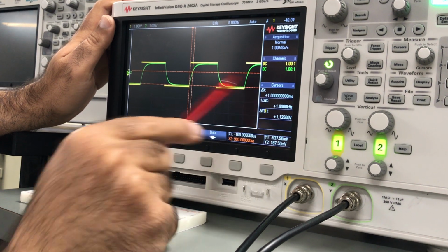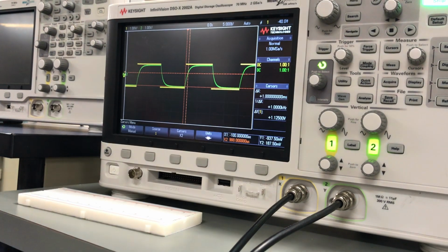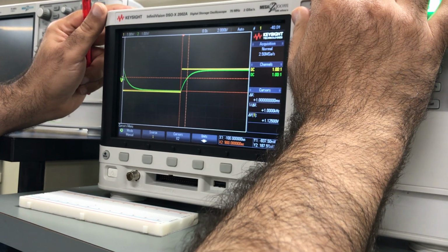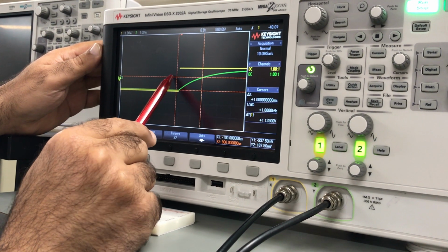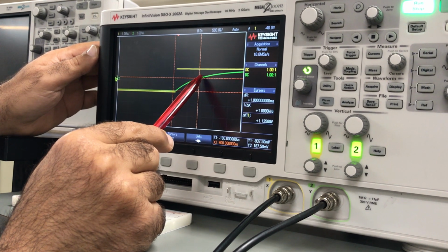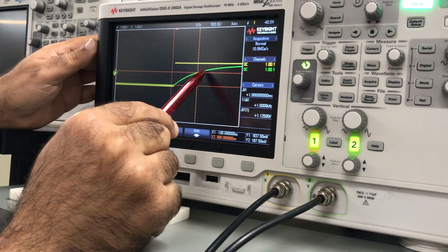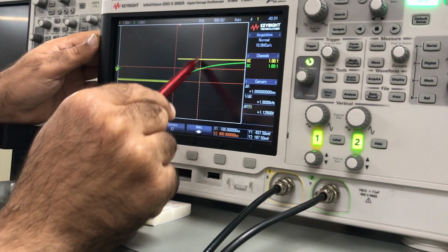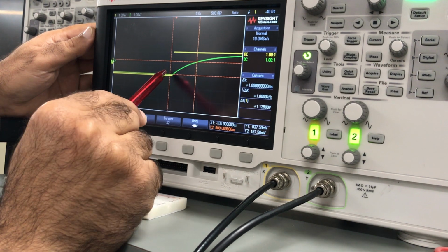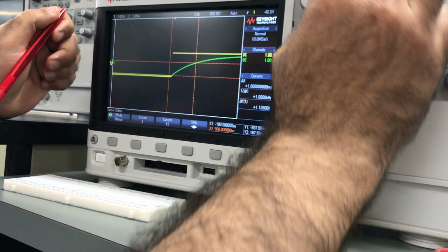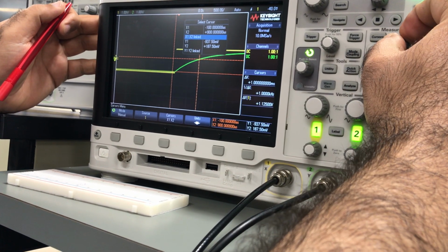If you try to calculate the time constant for RC, given R and given C, you will find it is equal to 1 millisecond. I can make this guy bigger a little bit. Like what you are seeing, this is the intersection between this x at 63.2% of this value and this line. I put my x here to find the difference between this guy and this guy, which is describing approximately the time constant. I can move this guy a little bit here to make it more accurate.